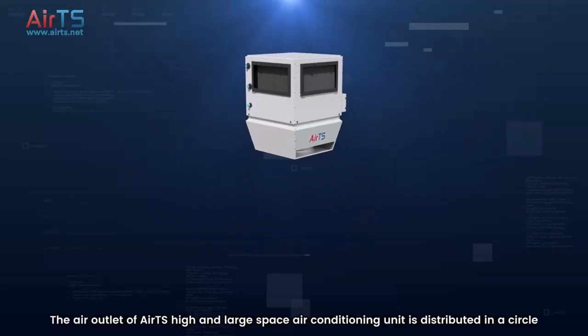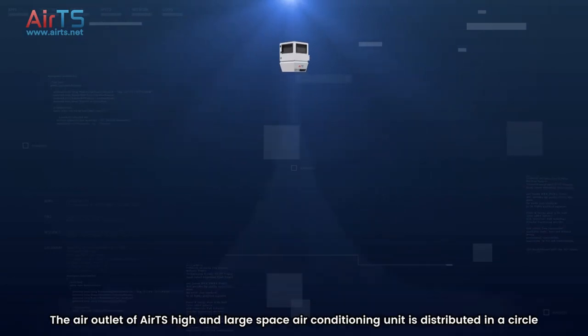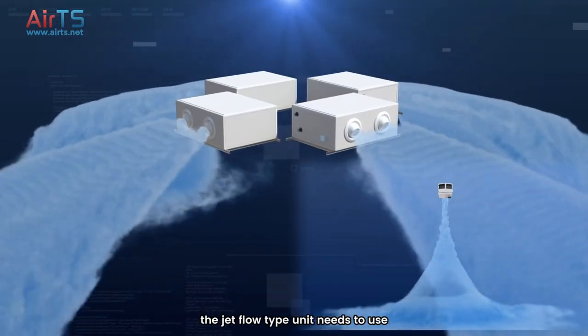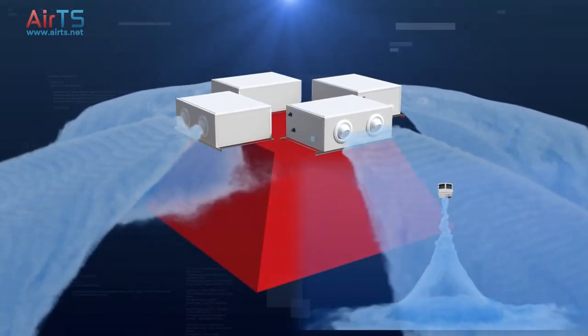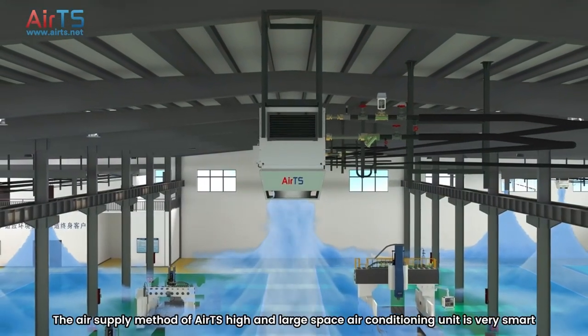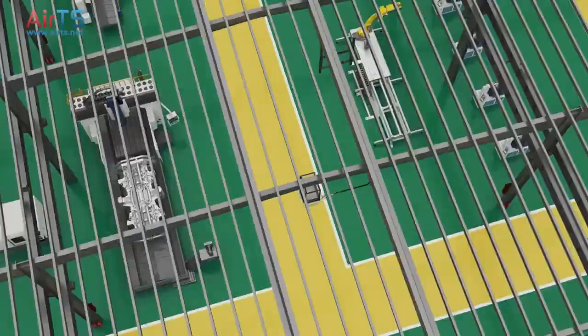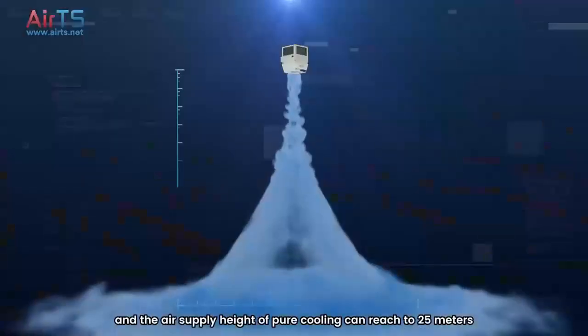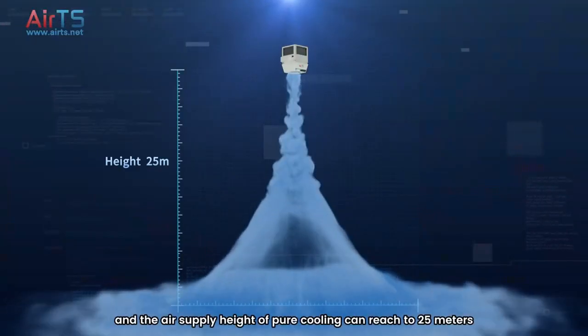The air outlet of the AirTS high and large space air conditioning unit is distributed in a circle. To achieve air supply from all directions, the jet flow type unit needs to use 4 devices and has blind angles. The air supply method of the AirTS high and large space air conditioning unit is very smart. The air distribution range of a single device can reach 1,200 square meters, and the air supply height of pure cooling can reach 25 meters.